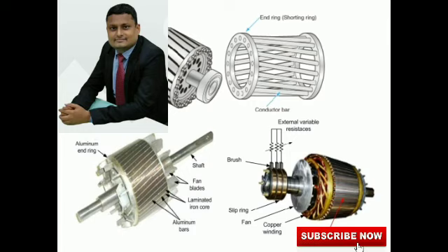So once again I am repeating the advantage of larger air gap: increase in overload capacity, also cooling gets increased, and reduced magnetic pull, reduced tooth pulsation, and reduced noise.